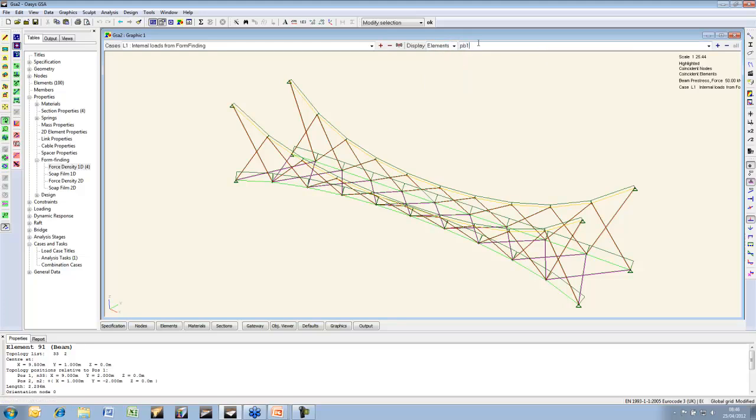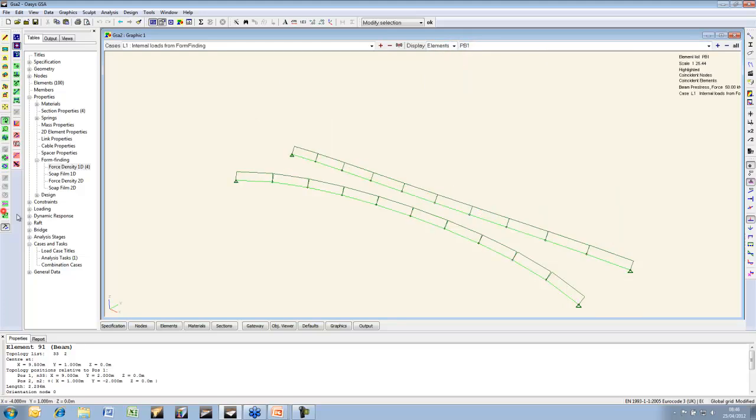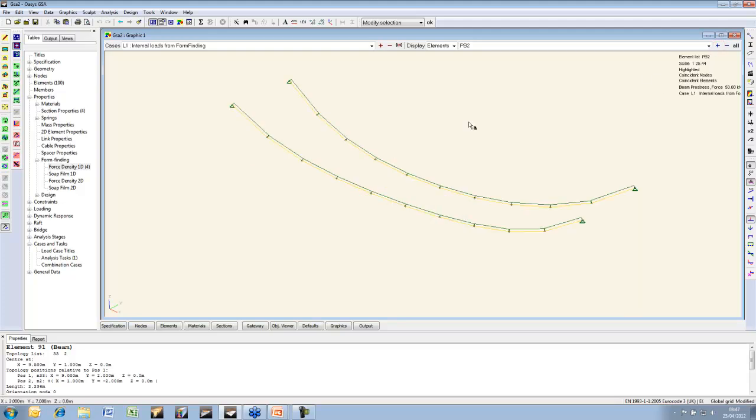Let's say property beam 1. And let's look at the values of those. So these were all 1 meter apart to begin with. Some of these are stretched, and so we're getting a force density of a pre-stress of a little bit over 40 for these, because again it is proportional to the length. Top bars, top cables 10. I'm getting generally pre-stress of 10.